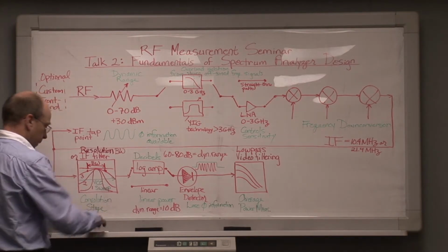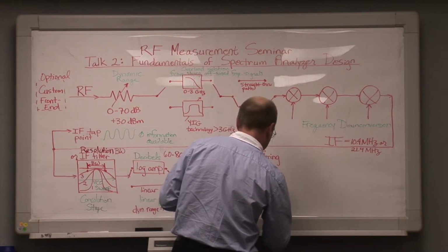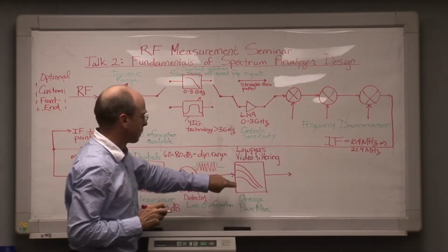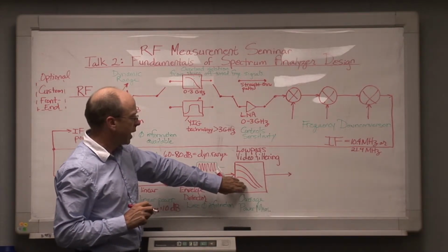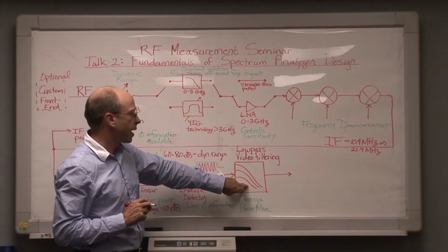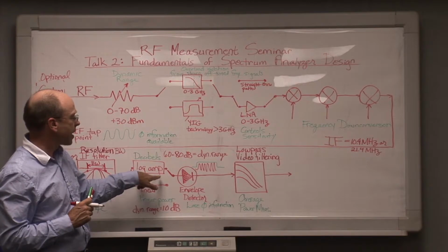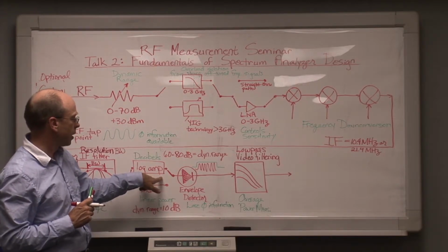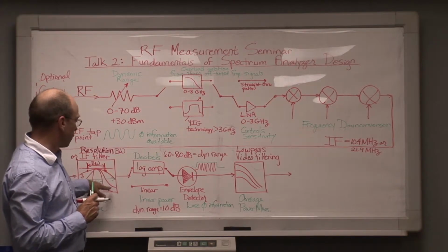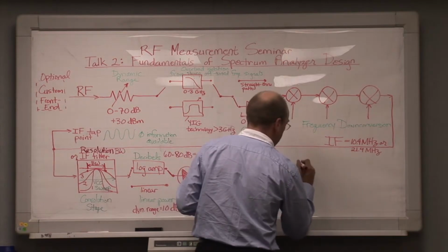Now, this stage is not required in modern digital spectrum analyzer designs, because in modern designs we have a discrete component root mean square functionality. We get that by actually being able to divide by 10 and take the anti-log of these numbers out of the log amp in a digital design, and we're able to, in effect, sample the waveform and calculate the root mean square directly.